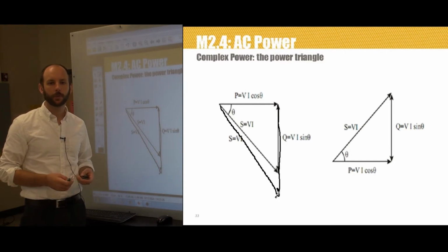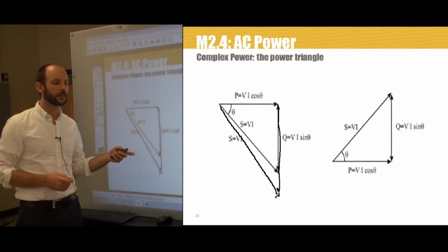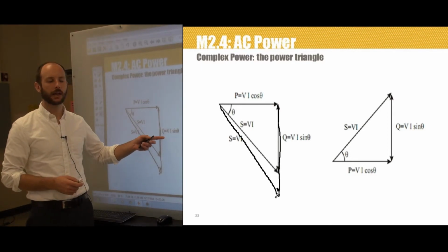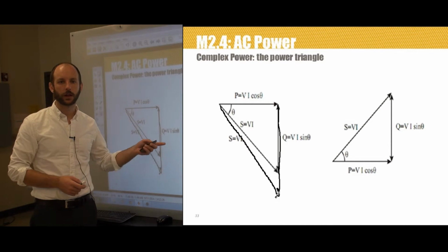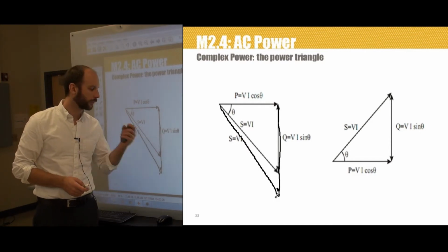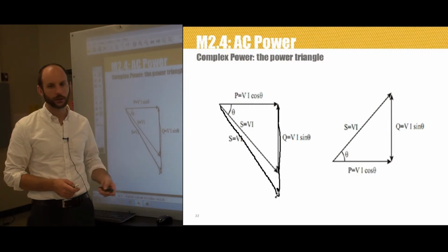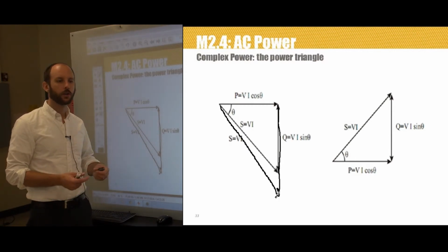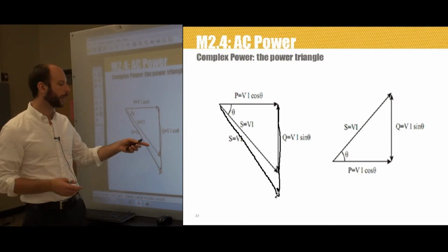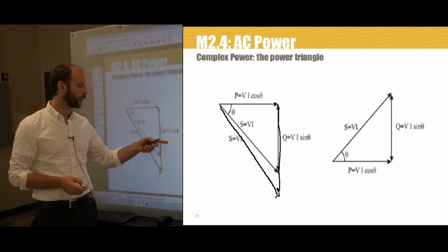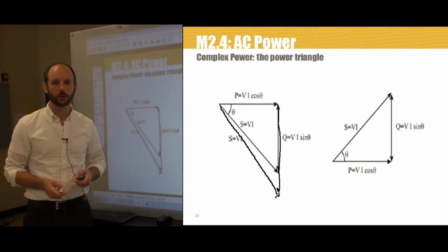Additionally, customers only pay for real power and not the infrastructure needed, not the big cables and everything needed to supply Q, although that is not true for industrial customers. They do pay for facility fees to supply Q. And so the electric company can't recoup a lot of that because they can't charge residential customers for Qs.